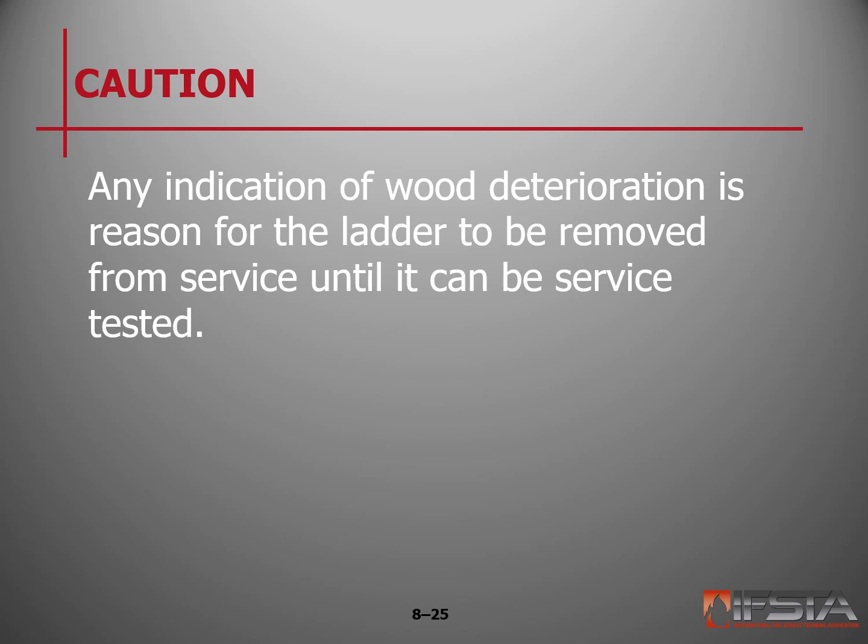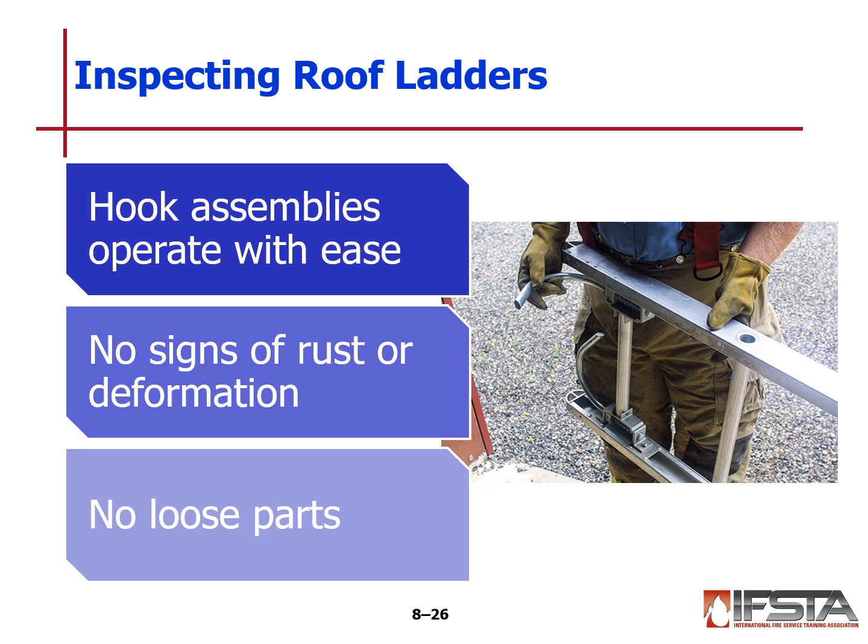So a caution here, any indication of wood deterioration is reason for the ladder to then be removed from service, basically until it can be service tested, repaired, service tested, and placed back in service.